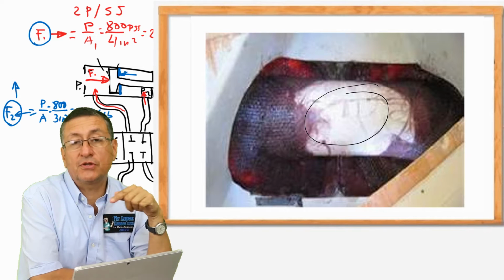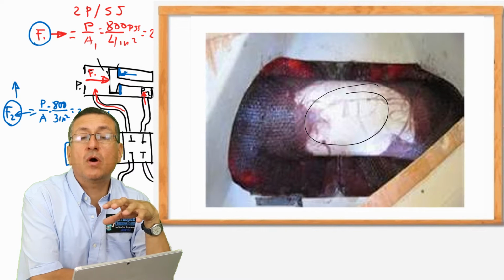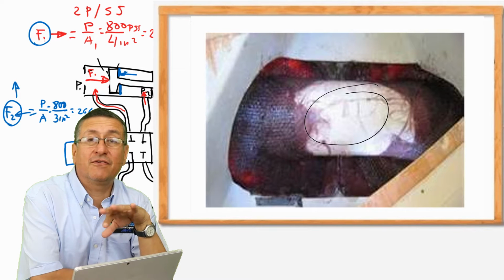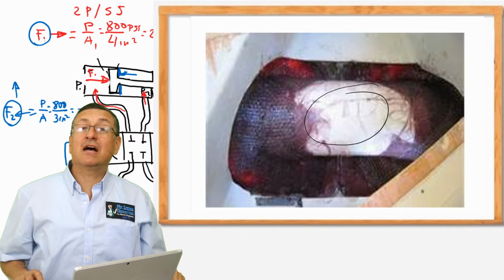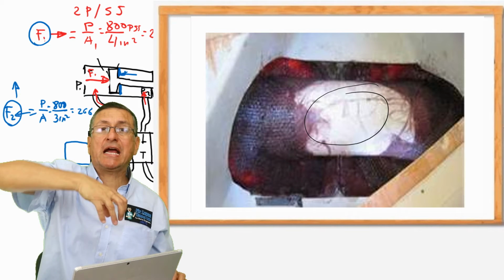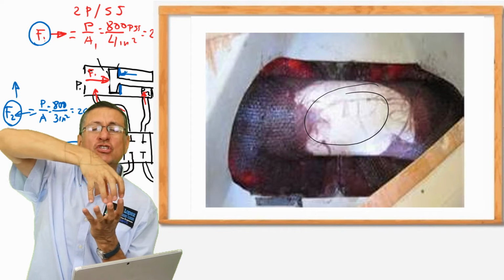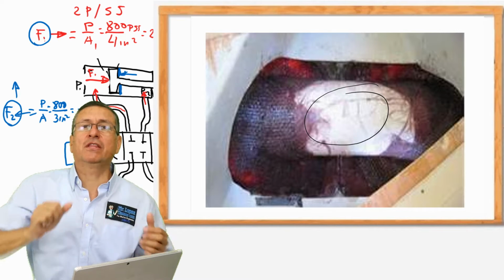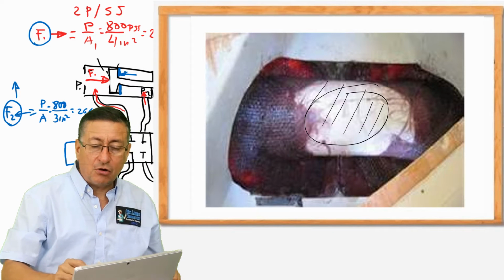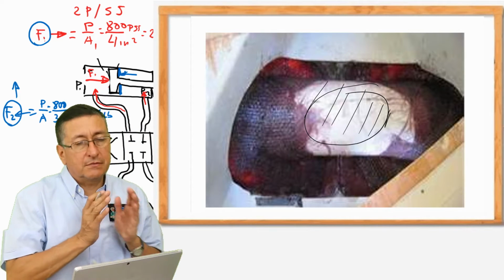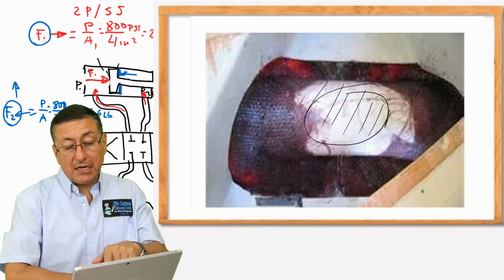I recommend you protect the middle of the tunnel with blue tape in order to avoid the resin and the fiber drying over there. Why? Because after that, when you try to install the bracket of the bow thruster, the bracket doesn't sit properly because of the resin over there. Protect this area. Try to keep this area completely clean. That's an important recommendation. Be careful with that.